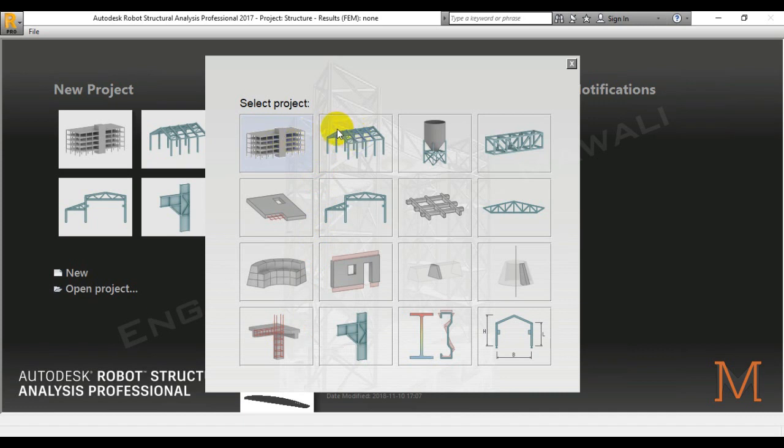Now, what are the differences between those two? In this one, you can use steel sections, but in this one there is seismic analysis. While in this one, if you're going to design only a hall or a hangar, there will be no seismic actions and no concrete at all. But in here there is concrete. So if you want to design a big steel building, then you have to take this one, a building design,